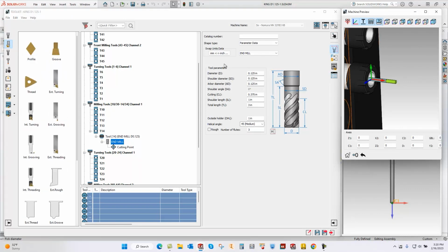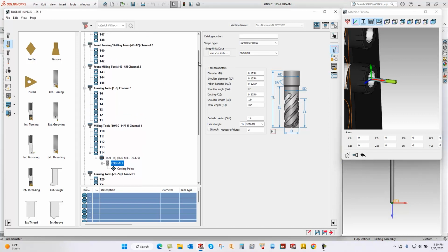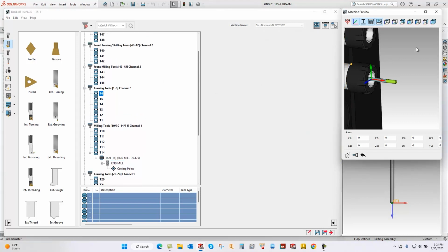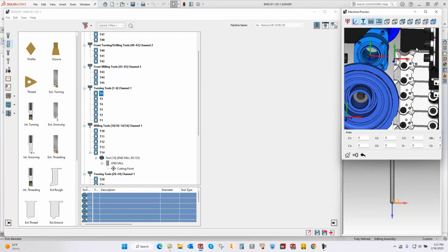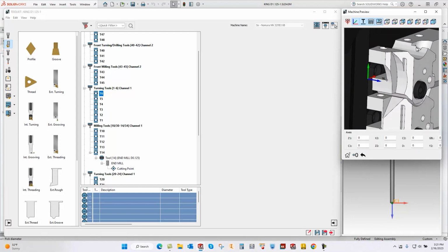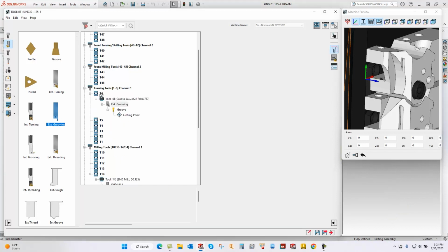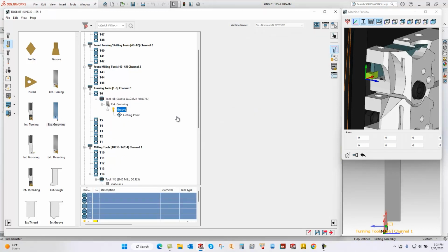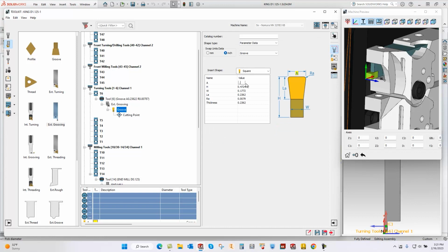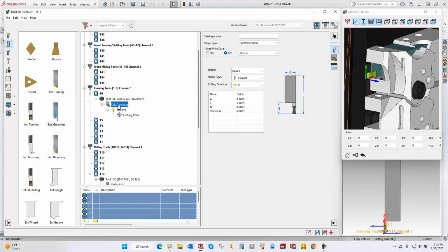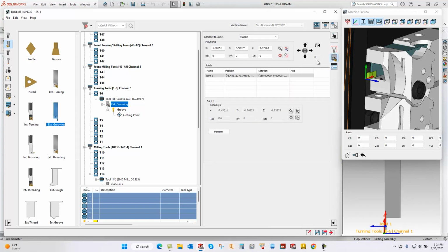We're going to go ahead and put one in the cutoff position, which is going to be number 6. So let's scroll over here. That's right up here. All right, that's our cutoff position. So let's go ahead and grab this one, and we'll drag it into position number 6. Now, real quick, I'm just going to make this 100 thousandths wide. That's what I generally use. But going back to the actual shank, I want a little more stick out here, so I'm going to make that 1 inch.